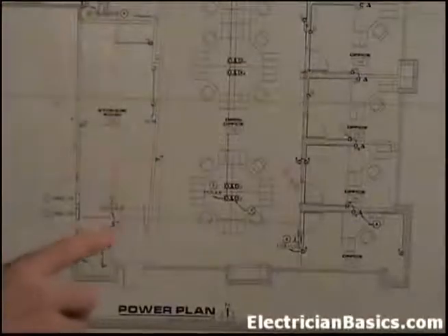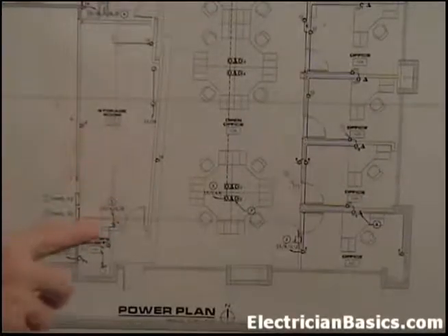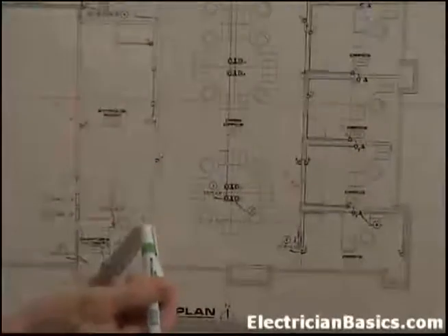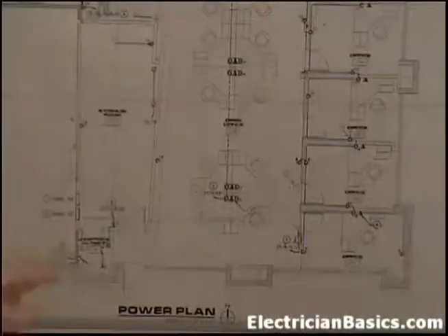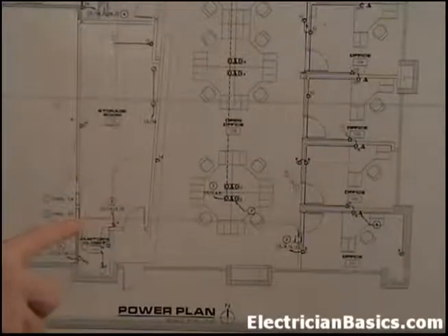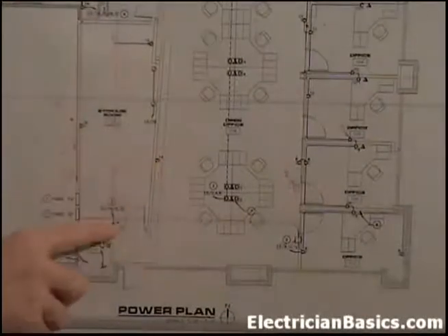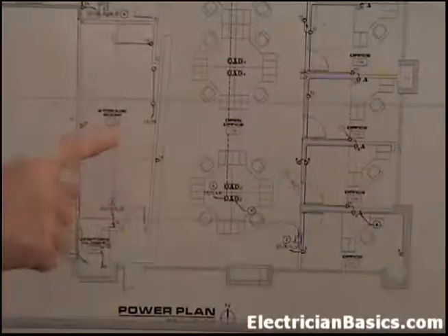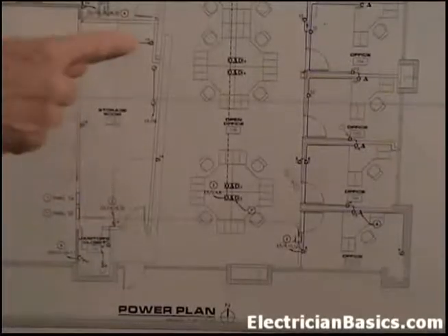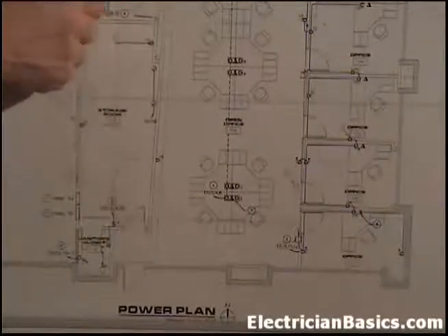But anyway, look at this. We have 14. Now on your page, you're going to see there's a black line going up to here where there was conduit, and a black line here where there was conduit. I've taken the whiteout marker and got rid of that, because the way it was built was a junction box here, and from this junction box they went to the panel. From this junction box it went to this circuit, and from this junction box they went here. They didn't go from here to here. Then from here they put in another junction box and went to here, so we could take this out, because we put another junction box. Then we went up here, put one in the middle, and went and got these.